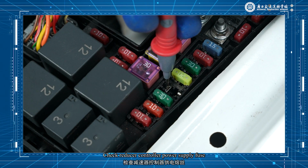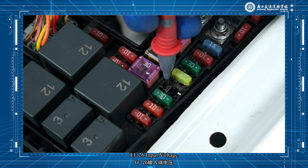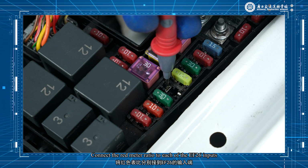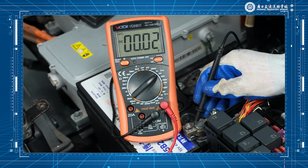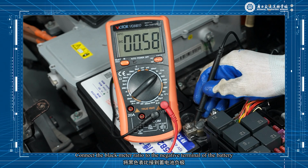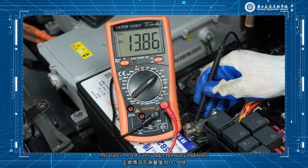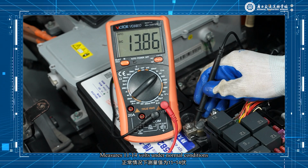Check the reducer controller power supply fuse. For the EF26 input voltage, connect the red pin to the input of EF26. Attach the black pin to the metal housing of the bodywork. Read the DC voltage value. It measures 11 to 14 volts under normal conditions.